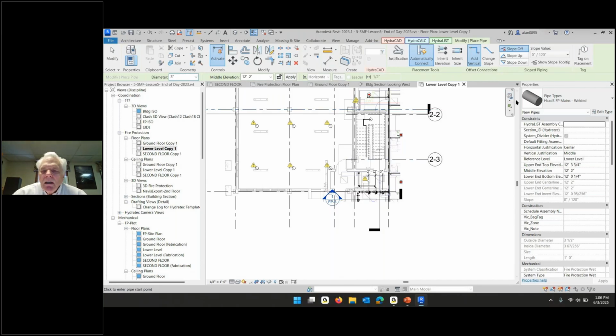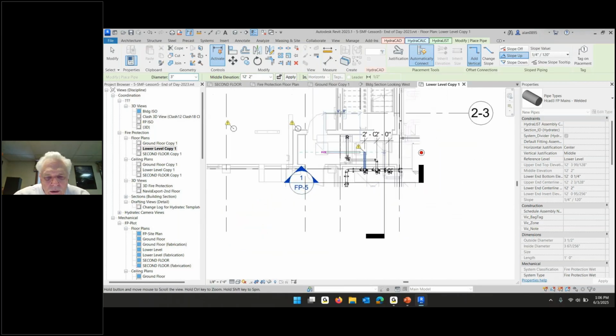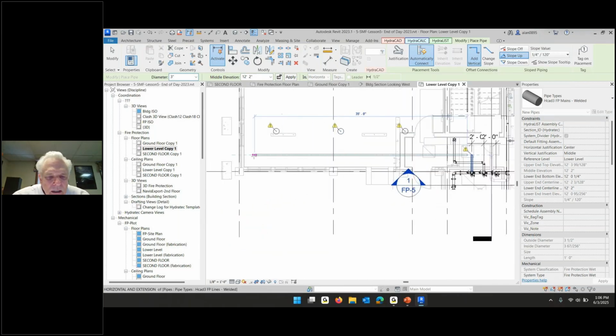And I'm going to slope up over here. I'm sloping up a half an inch in 120 inches, half an inch in 10 feet. I'm sorry, this is mains, only a quarter of an inch in 10 feet. So I'll start in the vicinity of this. I'm going to go shallow for now and get this thing all lined up first. And then I'm going to come down here.